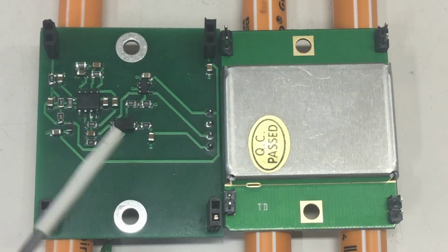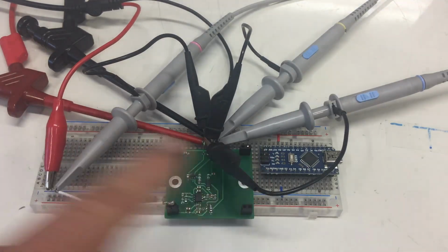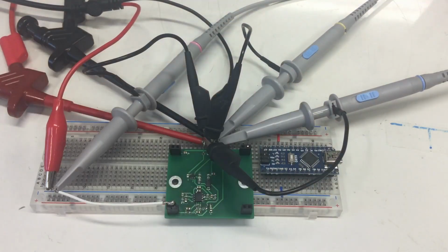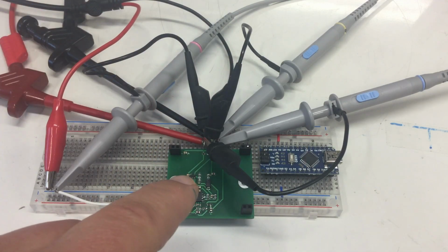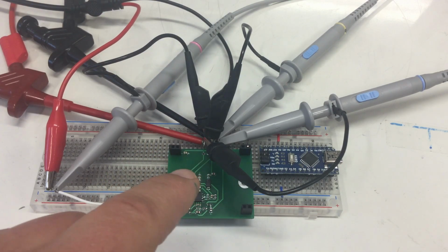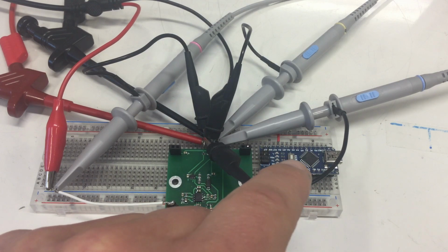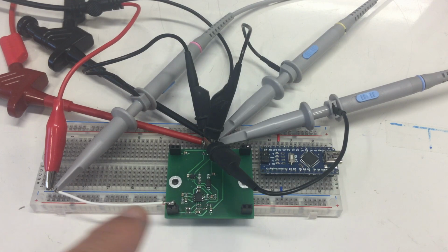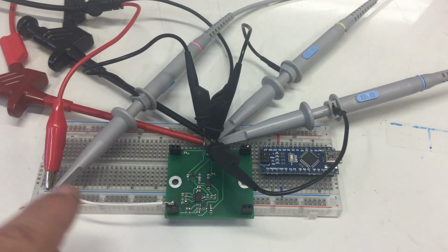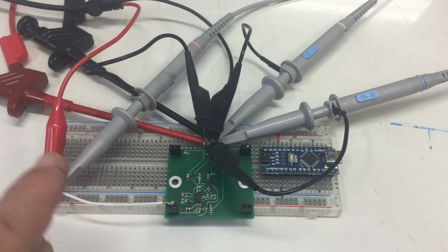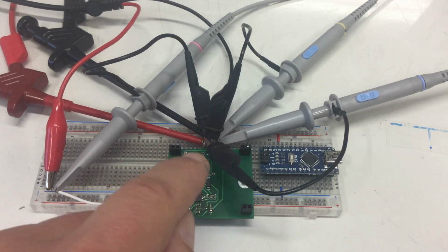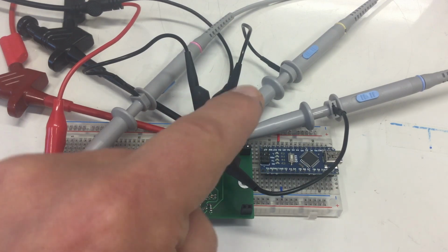Anyway, let's connect Limpkin's breakout board to a signal generator and the scope and see what it can do. I dare not touch or move anything here, so I will pan a little bit to show you what's on the bench. Anyway, there's our HB100 breakout module from Limpkin. You can ignore the Nano here, it's not connected. I'm feeding in here the intermediate frequency signal from a signal generator, and I connected that 4-pin header to 5 volts VCC and the outputs also to the scope.